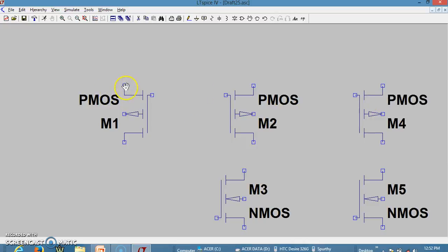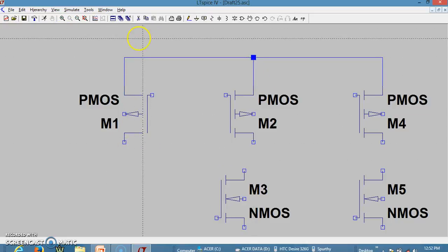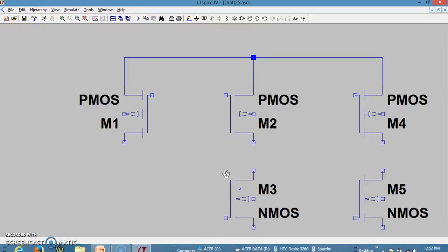Now this ensures that the source is connected to the VDD, and let me do this connection. So this is our VDD. So let me have this over here, and so have this, the connections are done. Let me slightly move this MOSFET so that it comes in line with this. Now let me make the connection of drain to source, this drain to source, and let us short this and this.